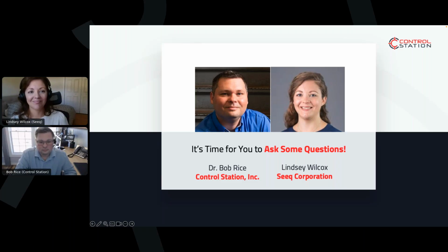That's great. And the last one, what different source of data is needed to perform this type of analysis? As far as sources and quality, you need good quality data if you're doing interaction analysis, frequency analysis, correlation analysis. You can't have 60-second data, right? You're going to need higher resolution data to do things like frequency analysis. If you have 60-second data, you're at best going to find 30 to 50-minute oscillations. You're not going to find anything that's high frequency.